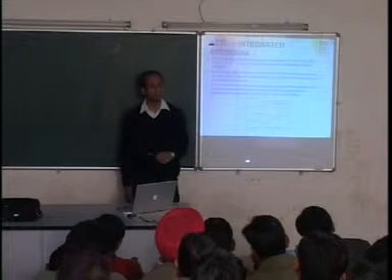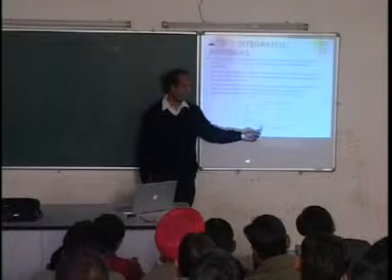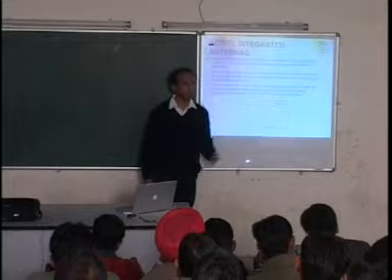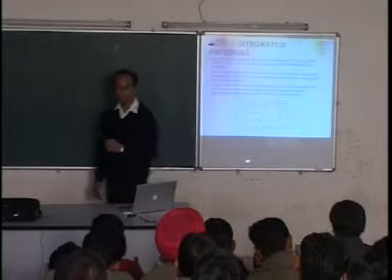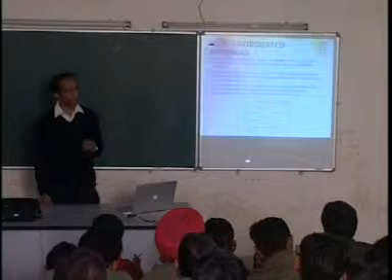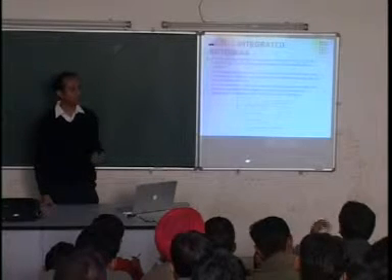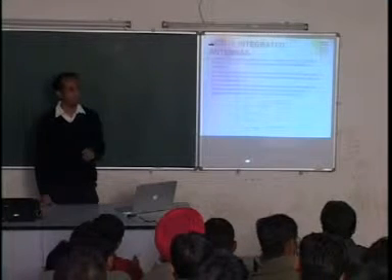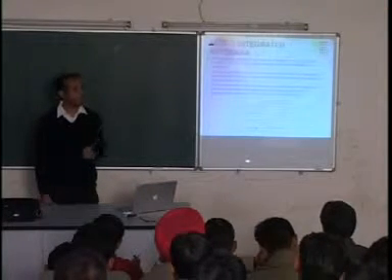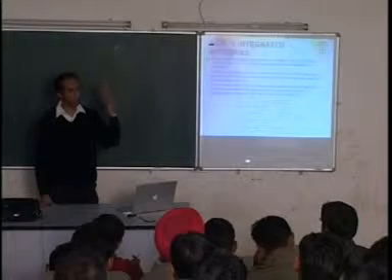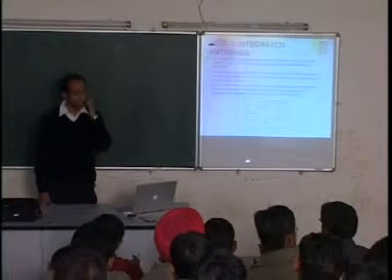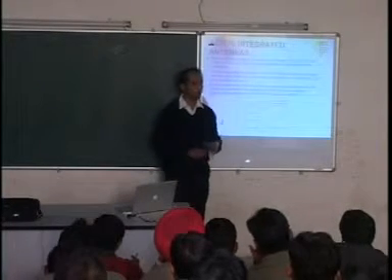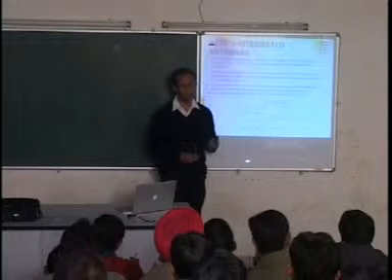Which means that if the gain here is sufficient and the loop length is properly tailored, that's why you have some length of transmission line, then you have oscillations. At what frequency? At the center frequency. What happens to the power generated by that oscillation is the key to the whole operation. The power is radiated out through the antenna. So this is a standard, very typical example of an active antenna. It is an oscillator cum radiator.